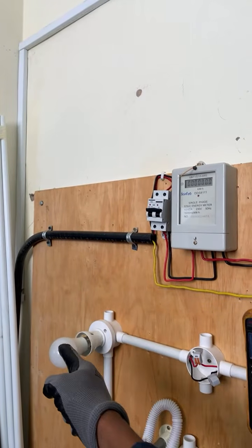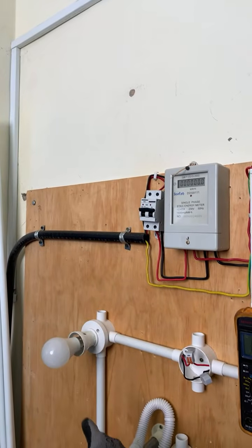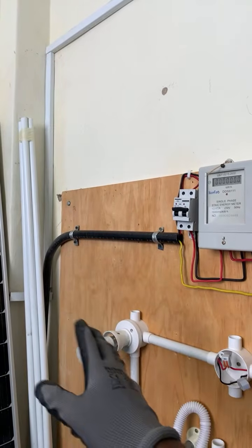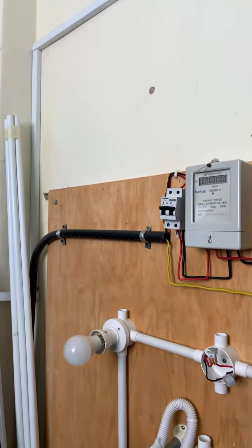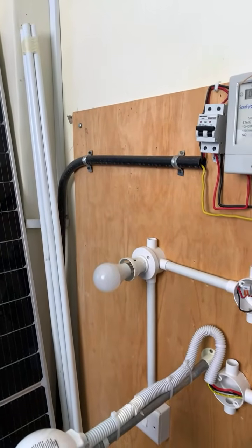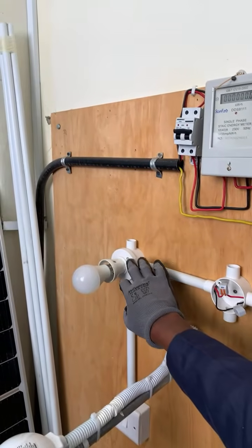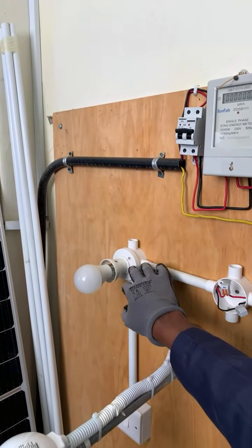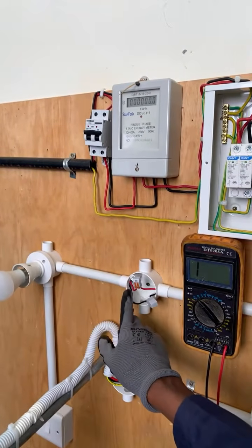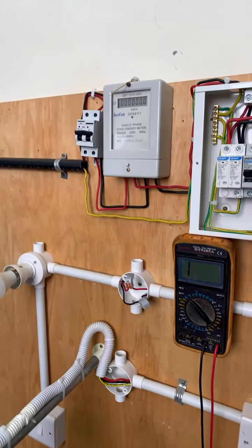There is a high chance that there is an internal fault in the lighting fixture, be it the bulb, be it a chandelier, whatever lighting fixture has been used there could have an internal issue. All right. Another problem is the holders. If, for instance, there is a short circuit in the holders, it could lead to that short circuit. And another culprit could be here. Here, most likely. Why there?